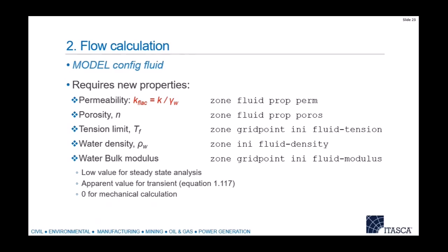Note that you're setting the water bulk modulus here, and this is a super important property because this is basically how stiff water is. Now, as we all know, water is pretty stiff. And if you're doing mining, this might not be a big deal because the rock you're dealing with is also pretty stiff. If you're doing soils, there can be a big difference between the actual real fluid modulus and the soil modulus, and that can cause numeric problems and a lot of trouble. And so you end up playing a lot of games, adjusting your fluid modulus to give you an accurate response without taking forever. We're going to talk more about that later, hopefully, okay?